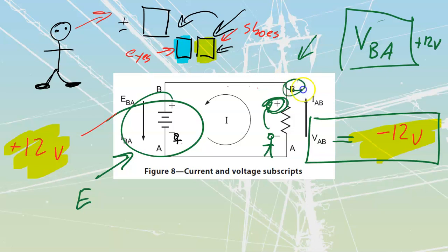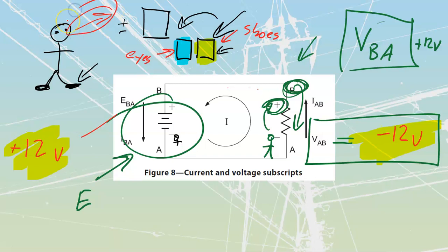And that would be if I were standing up top here on the B, looking down that way. If I were standing on the A, looking up towards the B, I see that it would be a positive 12 volts. So it's just a reference. You do this all the time with your meters at work. If you've got a DC circuit, you can go and take your meter leads and you've got a black lead, which is your reference. Guess what? Look at this. I'm wearing black shoes over here. And you've got a red lead. Look at this. We have got red laser eyesight over here. That's what your meter is doing.